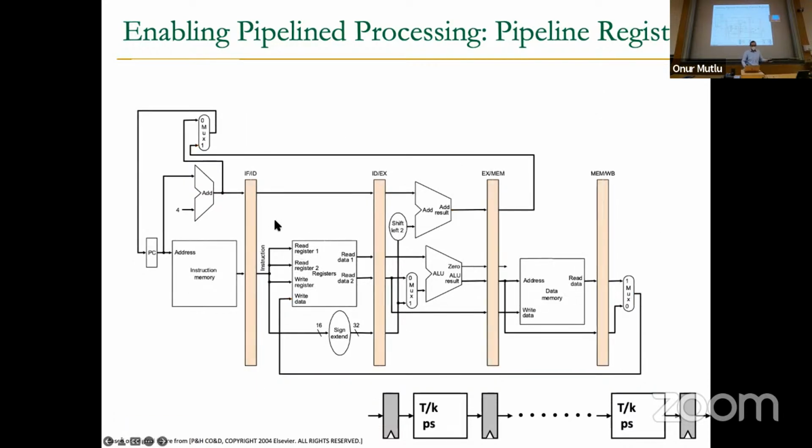They look nice. And we name them, this could be called the fetch stage register, but instruction fetch / instruction decode register, instruction decode / execute register. Basically, they take the name of the stage previous to it and the stage after it. Execute / memory register and memory / write back register. So you need 4 registers.